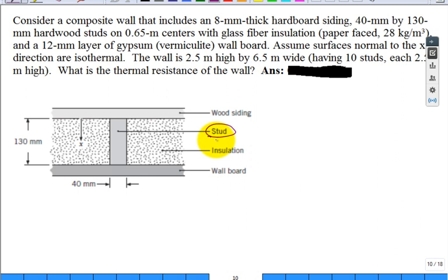But I'm telling you, some words are confusing when you first see them. Like, what's that? A stud. Really? All right. Now, a lot of them up north are 2 inches by 6 inches. That's just because up north they have long winters and they need more insulation in the walls. It's cost effective to build with a 2x6. Everything around here is a 2x4, unless they've moved. Anybody know if they've built a house with a 2x6 wall around here? I've never seen it. But up north it's extremely common, 2x6.